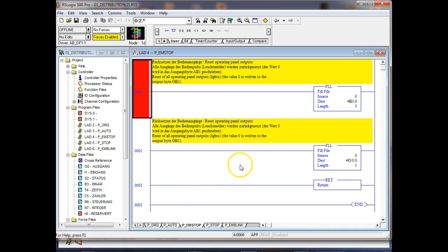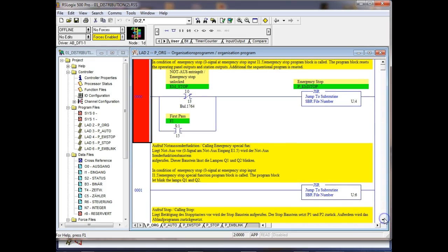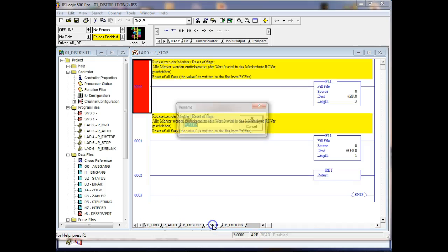Okay. And then what would it do if I go back to my original one? It says jump to subroutine what? Now this is conditional. This is a conditional JSR, right? You understand that? This right here is an unconditional. So that means every time it hits run 1, it's going to go to subroutine file 6, right? And this would be file 6. So this would be 2, 3, 4, 5, 6. Now what does this subroutine handle?